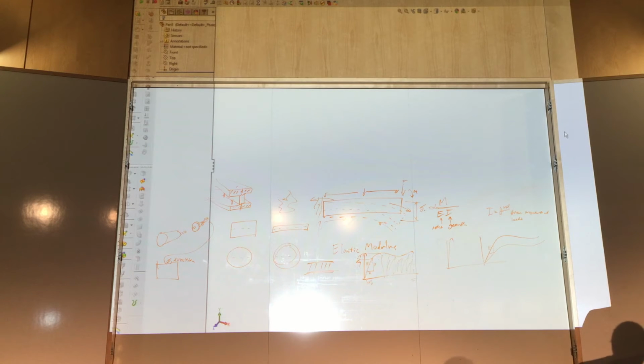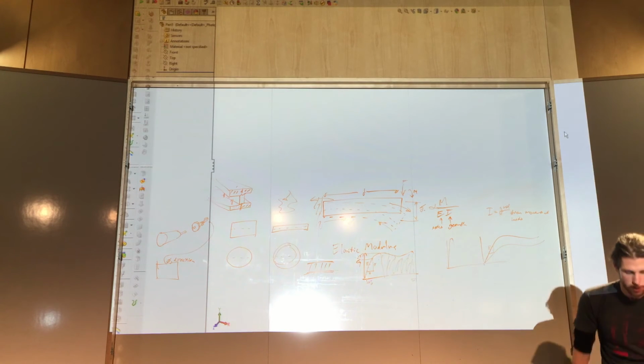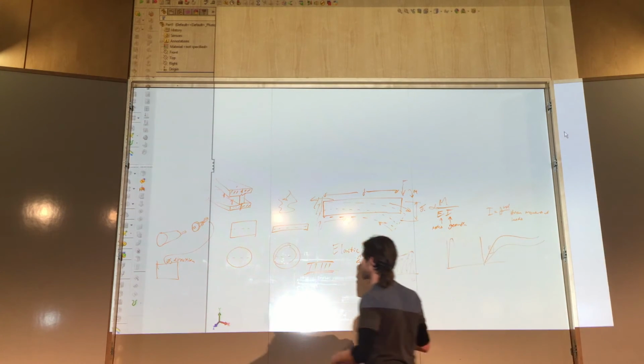What I really should do is control which degrees of freedom I'm trying to prevent from being over constrained. But I got lazy and just put a piece of rubber in there, and I said that was okay for my purposes. But you do want to look at where your constraints actually are. So that's one quick, easy thing for you guys.